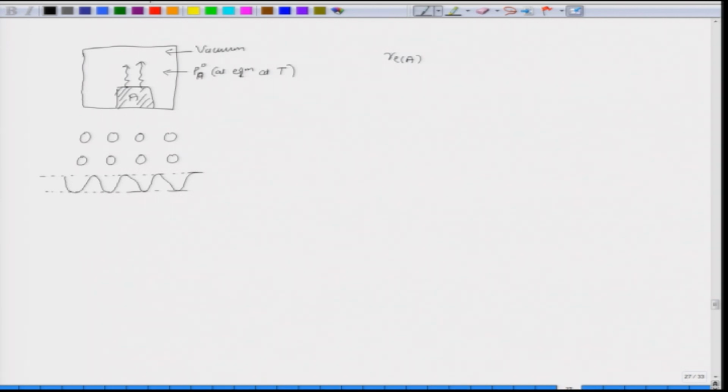So these are the equilibrium positions, which means at these positions or at the regular lattice sites the forces are balanced, there are interactions between the atoms, but at the equilibrium positions these interactions are balanced, right. So essentially those are the minimum energy positions. So those are the potential energy wells. If all the atoms are identical, right, the depth of these potential energy wells is the same, let us call it EA.